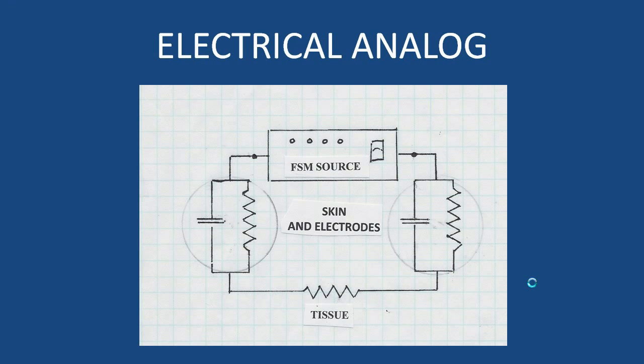The skin is modeled as a parallel resistance and capacitance. Values of skin resistance in the literature vary from about 10,000 ohms to 10 to the 6 ohms. The parallel capacitance is measured as roughly 0.01 microfarads. For the finite element QuickField model, these values must be expressed in usual scientific units.